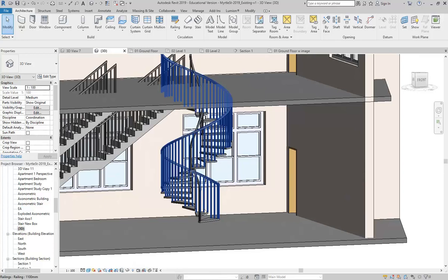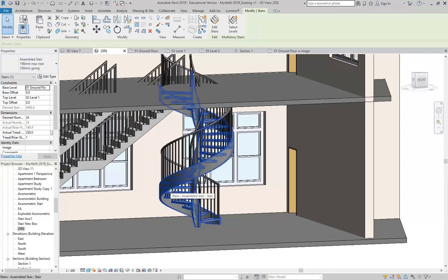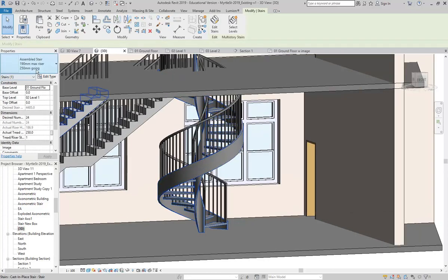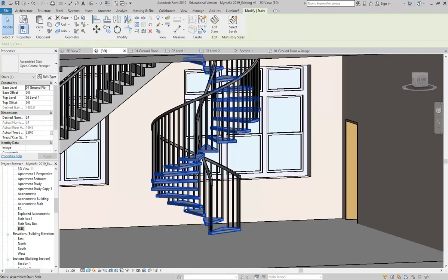Okay, so that's what you'll get with these nice full step spiral stairs. Let's change it back to the housed one. Well, in fact, I'll go to the centre one because that's a bit nicer. Okay, so any reason why you can see that's a problem now in Australia, to do a stair like that? Why don't you see them anymore in Australia? It's the same as what you said before. Yeah, exactly, it is. Because you need a landing every 18 steps. How do you get a landing into a stair like that? Pretty much impossible. So, yeah, because of that 18.